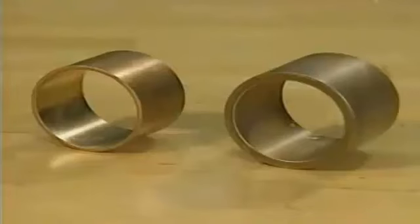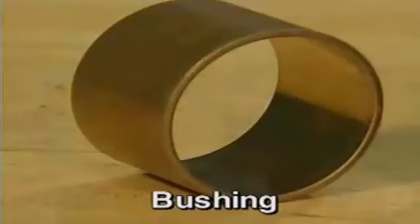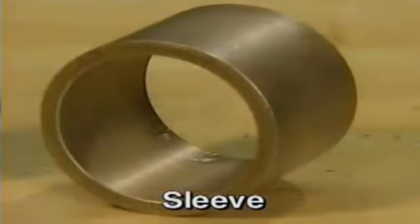Here are two examples of solid journal bearings. A solid journal bearing is sometimes called a bushing or a sleeve bearing, depending on its thickness. A bushing is a solid cylinder of relatively thin metal that receives most of its strength from the housing in which it is mounted. The term sleeve bearing usually refers to a thick-walled type of solid journal bearing.